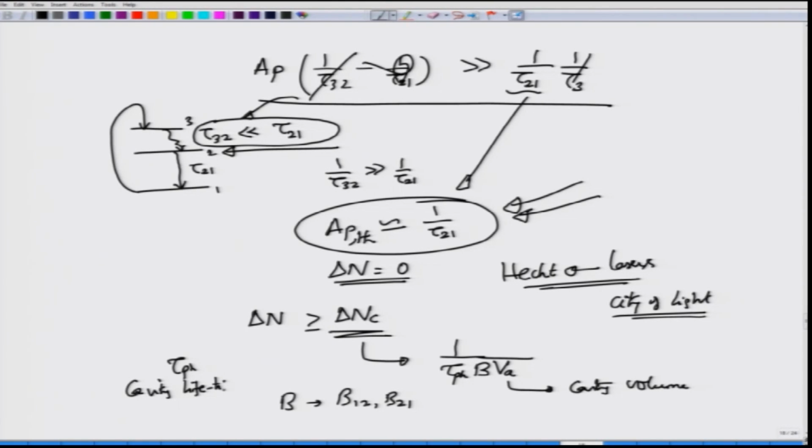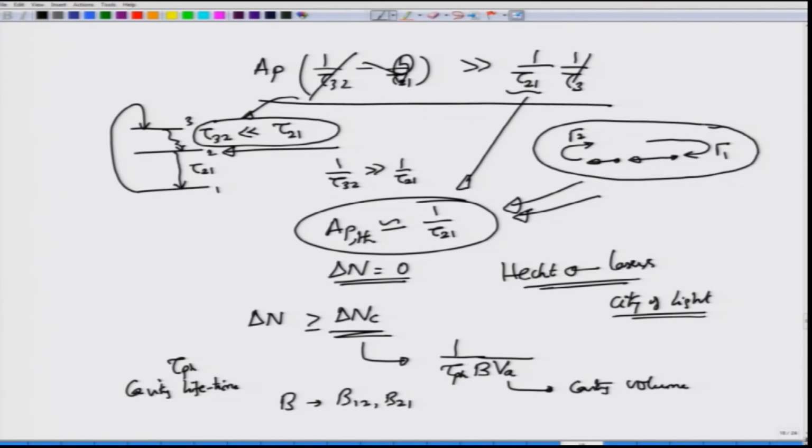This cavity lifetime has to do with the reflection coefficient at the first mirror, the passage or the gain here, the attenuation in the medium which is not gain, and then there is a reflection back onto the second mirror, gamma 2. So, cavity lifetime is essentially the effective lifetime of a photon which is stimulated emitted, but it would statistically remain in that cavity before escaping out from the first mirror. So, a mirror with a reflection coefficient that is less than 100%.